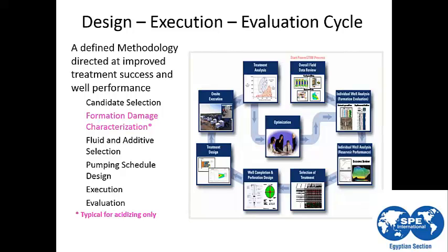Once we decide our objective from this stimulation, we can then decide the fluid and the additives that we are going to use. After that, we can design the pumping schedule according to the required frac geometry.